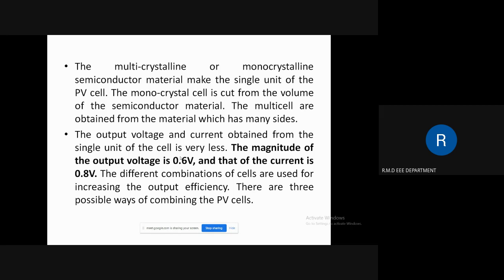So, till now we have seen the solar cell and the IV characteristics of it for a single cell or a panel. But many photovoltaic arrays are made up of smaller PV panels connected together. And the IV characteristics of a PV array is just a scaled up version of the single solar cell IV characteristics. The solar panel IV characteristics: the photovoltaic panels can be wired or connected together either in series or parallel combination or both to increase the voltage or current capability of the solar array.